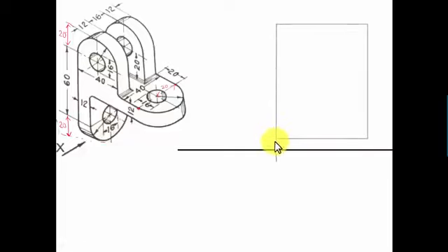That's it. Now we're going to kick off our drawing with this point over here. It cannot be seen exactly, but this point appears as if we need to travel a distance of 12 millimeters. The point is right over here, and it would appear as if there is a strip of 12 millimeters. So let's make a 12 millimeter strip, and then from here we go upstairs until we reach this center line. This is 60 and down below it's 20, so I'll be traveling a distance of 80 millimeters until we reach here.